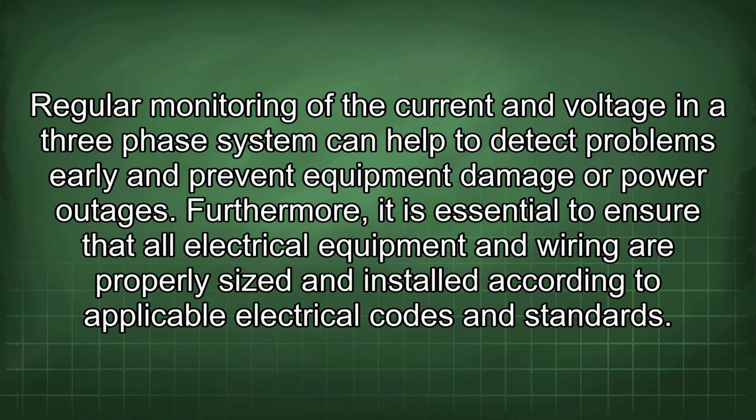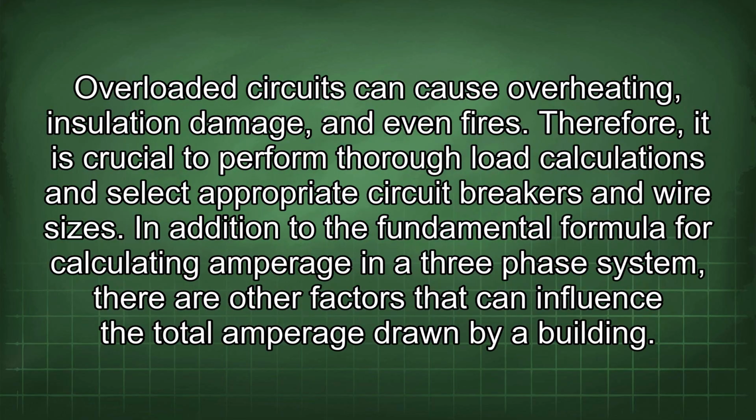Regular monitoring of the current and voltage in a three-phase system can help to detect problems early and prevent equipment damage or power outages. Furthermore, it is essential to ensure that all electrical equipment and wiring are properly sized and installed according to applicable electrical codes and standards. Overloaded circuits can cause overheating, insulation damage, and even fires. Therefore, it is crucial to perform thorough load calculations and select appropriate circuit breakers and wire sizes.